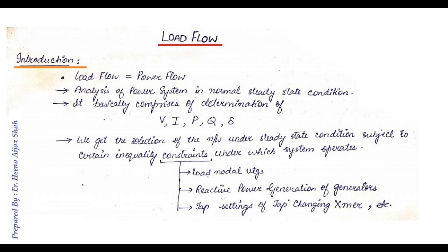After that, if we have to know about the stability of the system, we will analyze the impedance matrix. Or if we want to know about the faults in the system, then we will use the Z bus matrix. So what I want to say is, in load flow analysis, we actually deal with the system using matrices. We make a matrix, then we solve that matrix, and after that we get the required solution.